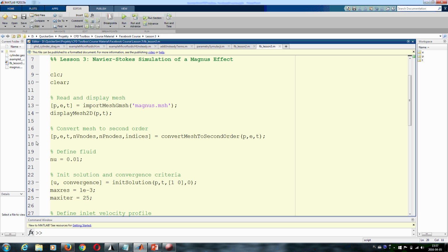Basically, this viscosity means that we will work at Reynolds number equal to 100. So certainly a laminar flow, and we will get a steady state solution. You might experience oscillatory solution and some problems with convergence if you go to high Reynolds numbers, because then basically the physics is such that you haven't got any stable solution to the flow around the circular cylinder.